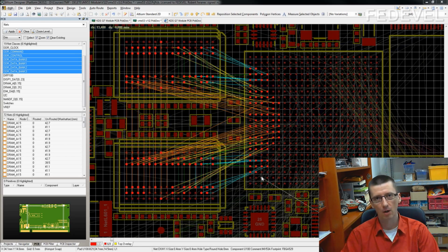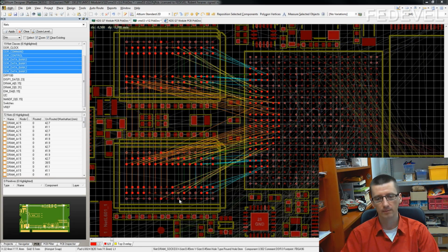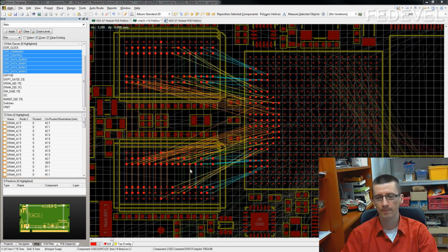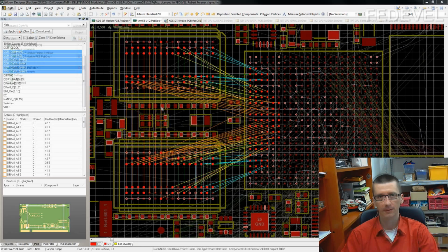We place there all the fan-outs, all the vias which should be there. Then we place the power fan-outs in the memory area, or if you use a slot, in the slot area. And then we just connect the memory. That's the first part. What do you think? What is the next step?